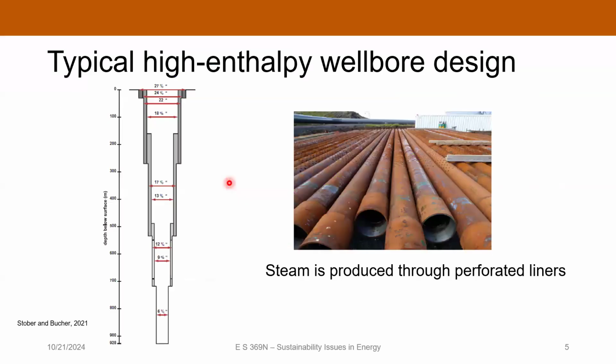Okay. So the deal with high enthalpy geothermal is that it's very hot. I guess that's probably obvious, but that introduces a number of challenges, and a lot of it is related to materials. A lot of the stuff we use in conventional oil and gas drilling is rated maybe to 180 degrees Celsius.